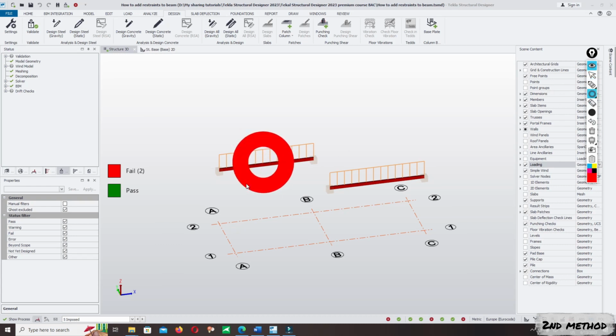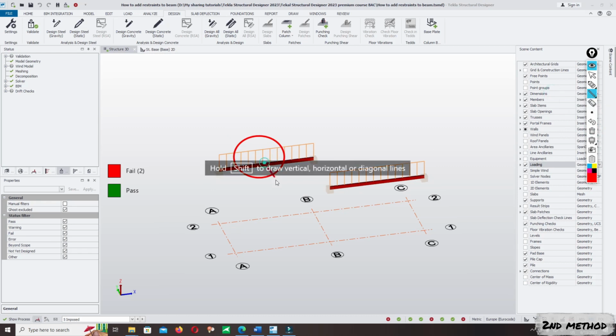This beam we design with the restraint at the center. Okay, the restraint at the center of beam. There are two sub-restraints connected to each other at the center of the main beam to prevent lateral torsional buckling occurring on this main beam. This is the concept when we apply during the modeling stage of the beam, and the second concept we can change it by using edit property.